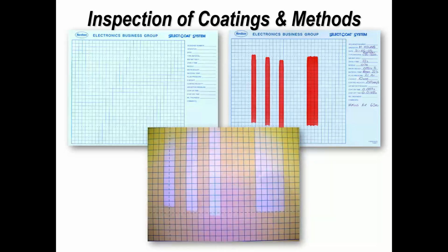And again, if you move to this one, we're looking at a coating which is a clear coating, but it's got a UV trace in, as opposed to the red coating you see in the top example. So again, both of these give you an indication. And because of the marked out square pattern, it looks for and demonstrates any overspray that you might have got. So with the red colored material, you would see that pretty easily. It would just be splattering at the edges. It wouldn't be a nice defined line, which is what you want your process to actually achieve for you.